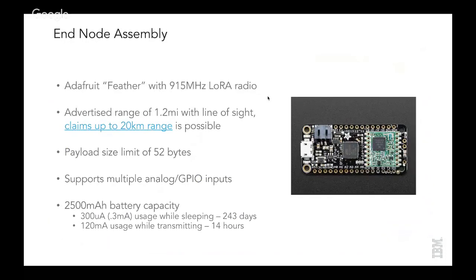Okay, so just moving forward. When the gateway was all connected, the next step was to assemble an end node to actually collect sensor data. In general, these end nodes are small microcontrollers, and you can generally use the Arduino IDE to place a C script on it, so it runs the C program in a loop. What that can do is sample the raw sensor data, format it, add additional metadata, such as time, location, and sensor type, and then send that off using the attached LoRa radio.